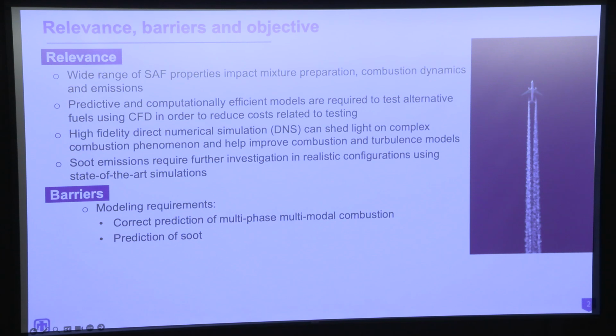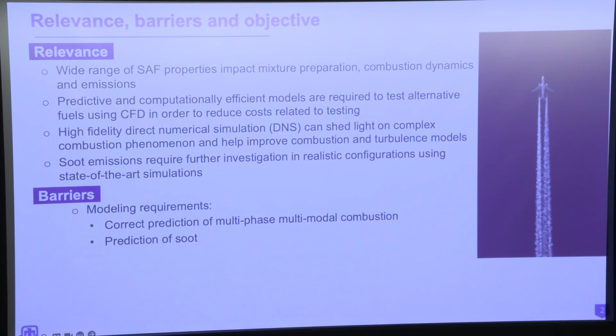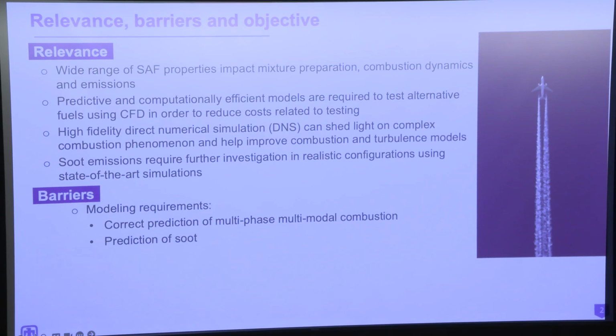And so some of the modeling requirements are, in addition to gas phase kinetics, this problem is highly multi-physics. You need to be able to predict multi-phase combustion, so spray evaporation and mixture formation, and also the combustion, especially for the conditions of lean blow-off or high-altitude relight or for cold start, can entail multi-modal combustion.